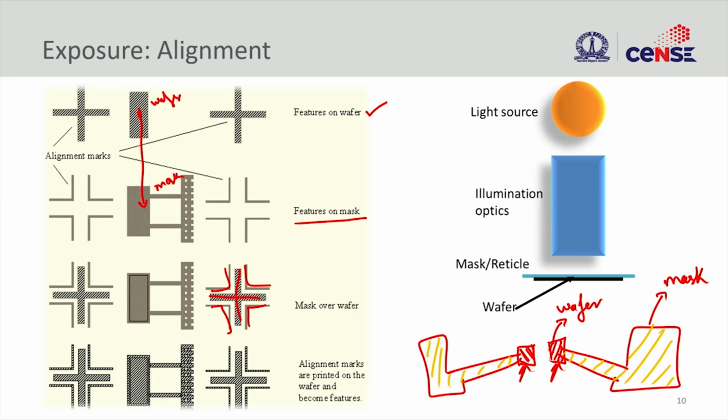So, it is better to put alignment markers and then only align the alignment markers, which should take care of device alignment as well, because this is all relative positioned. Once you have aligned, you put the contact and start illuminating, and you should be able to get the aligned illumination that you are looking for.